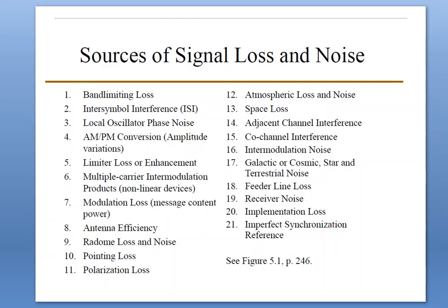Now coming to the third one, local oscillator phase noise. When a local oscillator is used in signal mixing, phase fluctuations or jitter add phase noise to the signals.